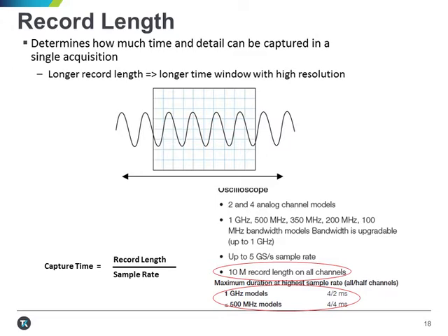But please remember, when you're using a digital oscilloscope, you can usually increase the sample rate by using a faster time scale up to its maximum. But faster sample rates eat up memory faster, so you'll need longer record length to acquire the more samples.